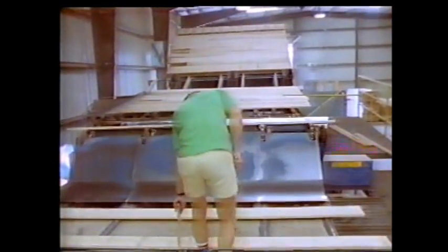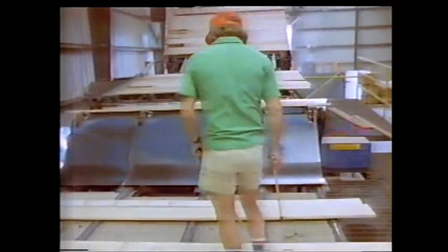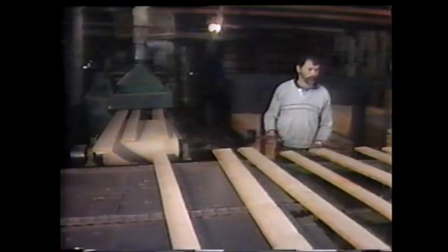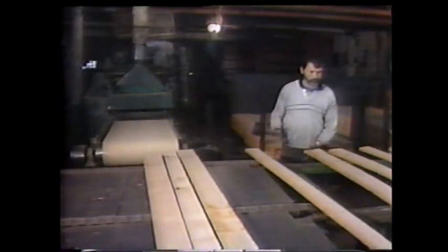An important fact to be remembered is that the experienced grader will grade a board according to how it will finish out at the standard surface thickness. So if a board has a stain or other defect that will not be present once the board is planed to its finished thickness, the defect will not be counted in the grading.